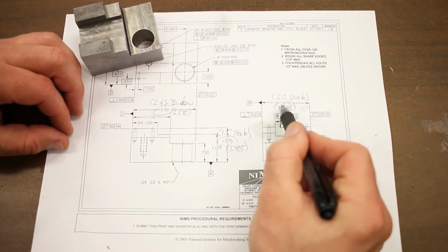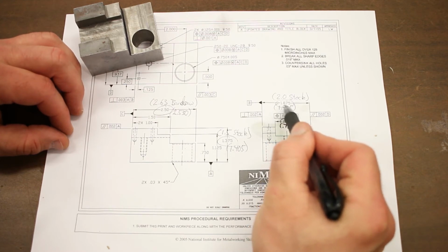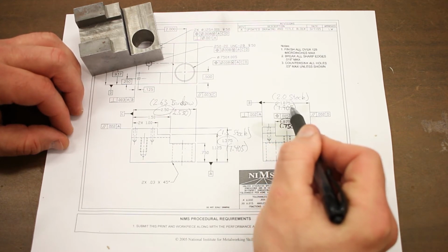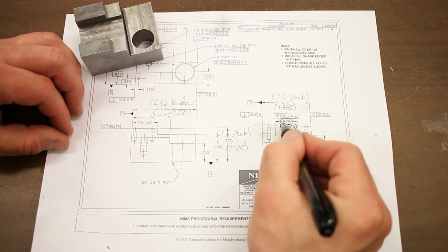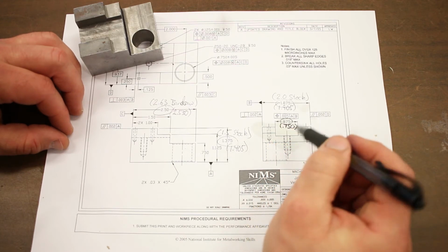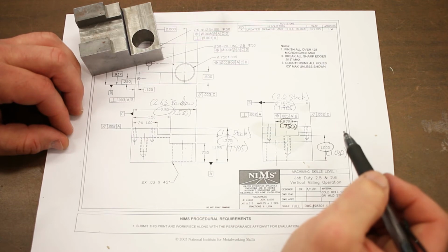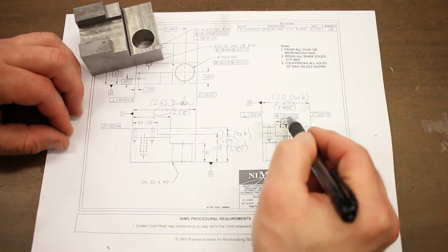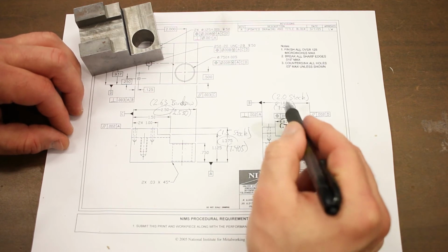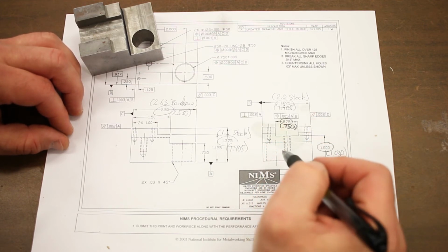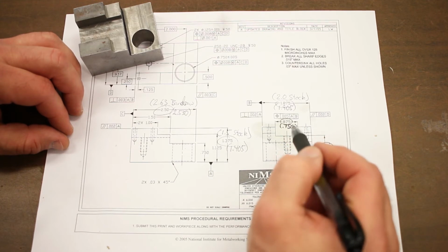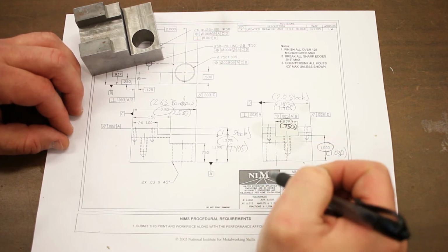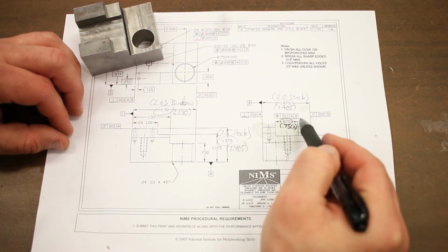Well, what this is getting at is that this length dimension has a tolerance, 3 decimal places, plus or minus 5 thousandths. And then the width of the slot also has a dimensional tolerance, right? That's also 3 decimal places, so plus or minus 5 thousandths. So this means that the center plane of the slot has to be positioned within 5 thousandths of an inch to the center plane of the part. Regardless of what the actual dimensions end up being, they want that slot to be right smack dab in the center of the part. That's the gist of it. That explains the datum B callout.